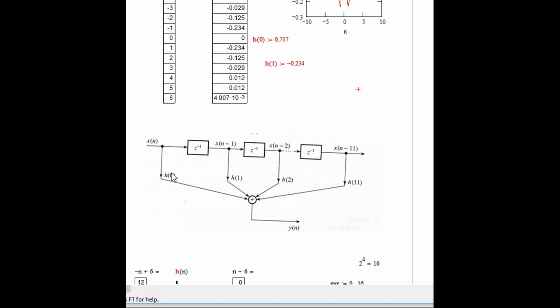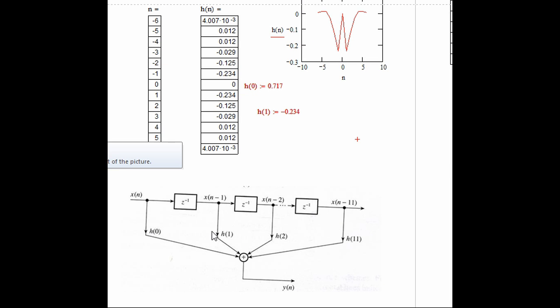And that value, I know it says H0 there, but because we use a windowing function, we actually have to add 13 to our n here. So you go, wait, say again, what did you mean? Yes, if you don't understand maths and I say add 13 to your n, what it actually means is that the value for minus 6 will be the first one.